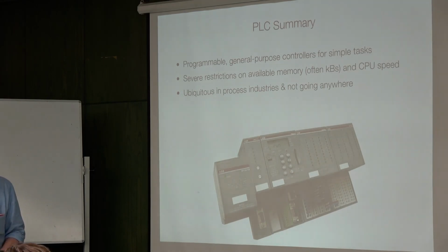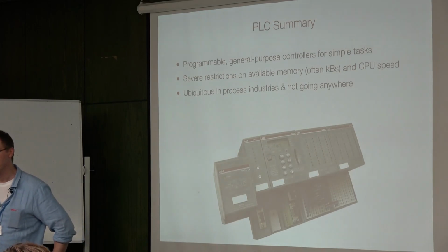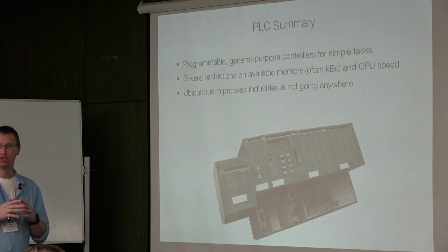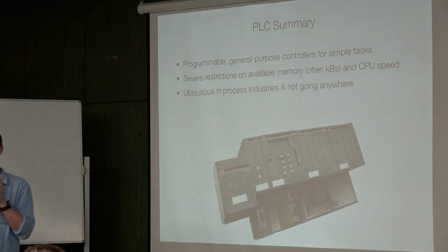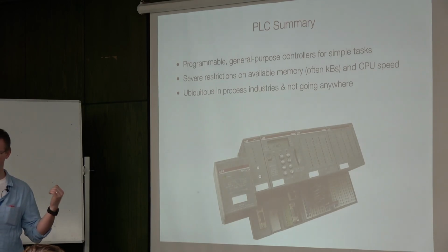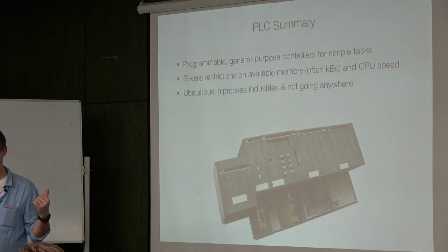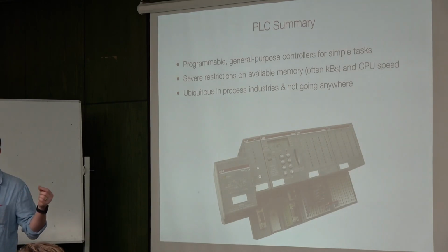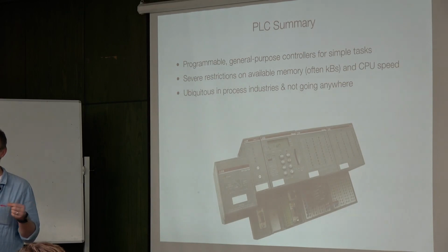Just one question. With this software, is it just a simulation environment, or can you also deploy the algorithm to any kind of PLC? Because I know that if you have a Siemens, then you have your own software, you have to use that. Okay, those languages are certified in a way that if you can extract the description, say, of the ladder diagram to a text file, and you can get the other PLC to interpret that, there is no loss of information. So they are really compatible.